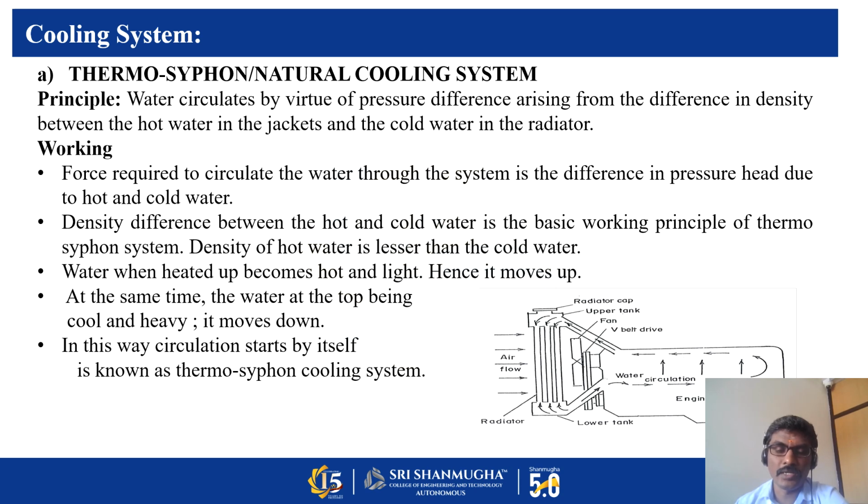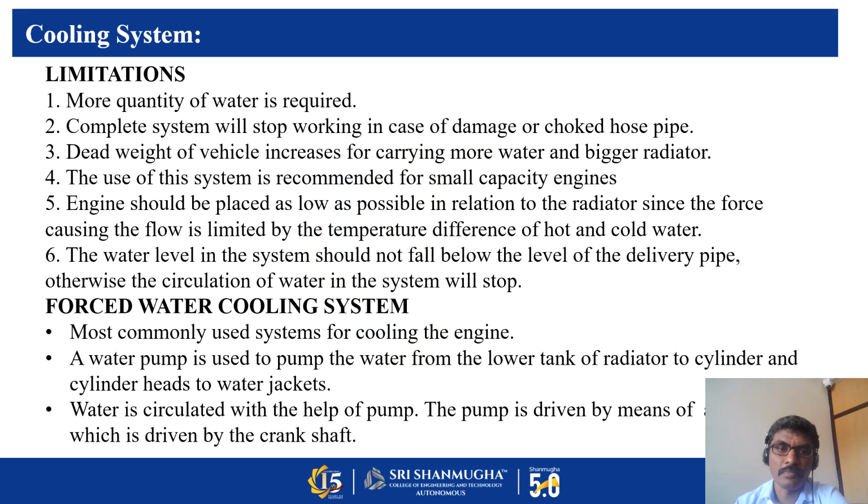So this water circulation, natural circulation, is called a thermosiphon cooling system. Limitation: more quantity of water is required. Complete system will stop working in case of damaging or choking of hose pipe. Dead weight of vehicle increases for carrying more water and a bigger radiator. The use of this system is recommended for small capacity engine. Then engine should be placed as low as possible in relation to the radiator, since the force causing the flow is limited by the temperature difference of hot and cold water.